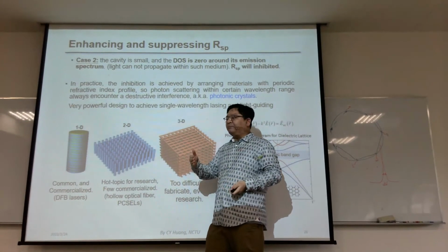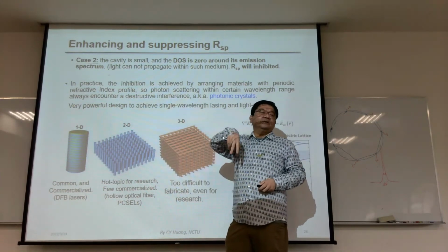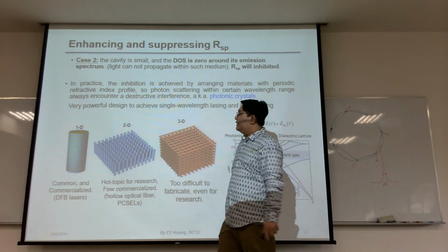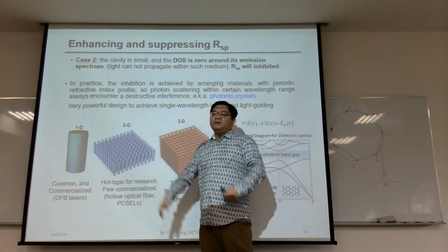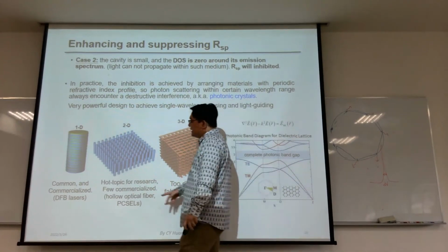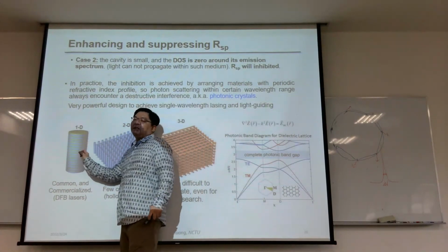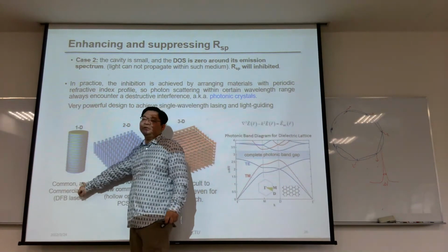I have some gain here, gain, loss, gain, loss. We do that with common processing and make the refractive index different along the epi wafer. So the processing is rather easy while the wavelength is long. So it has actual applications here.